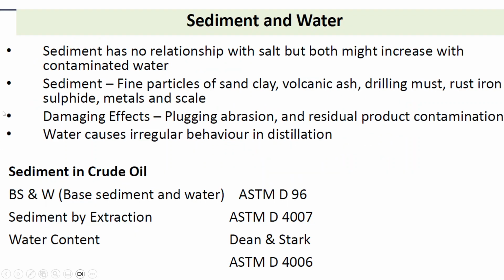Sediments and water. Sediments are different from salt. They are basically fine particles of sand, clay, volcanic ash, drilling mud, rust, iron sulfide, metals, and scales. The damaging effects done by them are plugging, abrasion, and residual product contamination. Water causes irregular behavior in distillation.